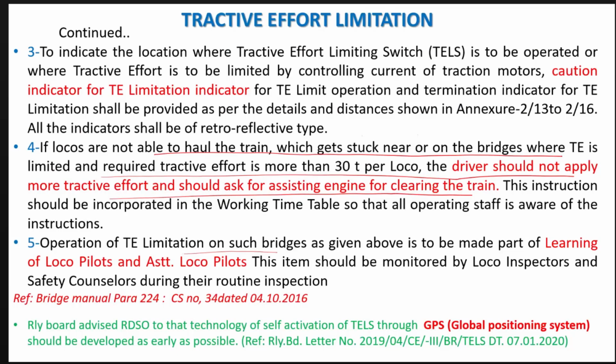In many cases I have checked and made a report to RDSO also in 2021, and at that time we checked that 95% of bridges which are considered critical for higher tractive efforts are not critical, because if the bridge approach gradient is not much, it is a smooth gradient, then the tractive efforts will not come so much, because the 50% component is the gradient.